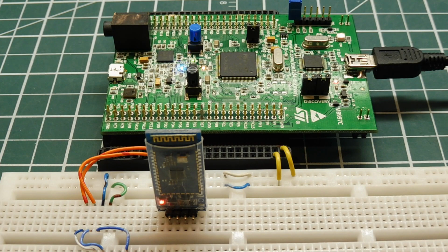Okay, that was my little primer on how to run a KISS, Keep It Simple, program on the ARM microcontroller using assembler and Forth. So when you get very familiar with the internal registers and buses of the ARM microcontroller, you could write your own direct register programming code and then assign that code to a Forth word. And you could build up your own high-level language. That's why NASA uses Forth in their space probes.